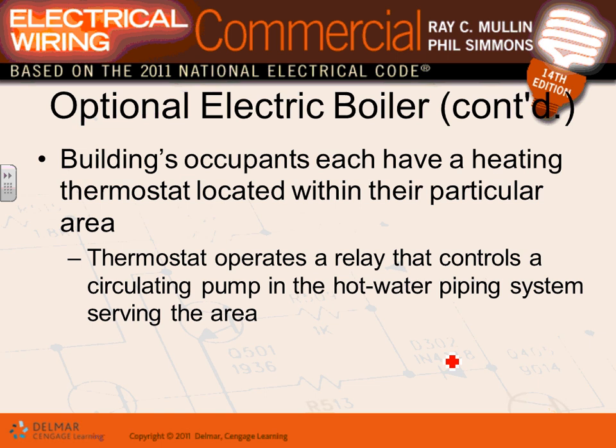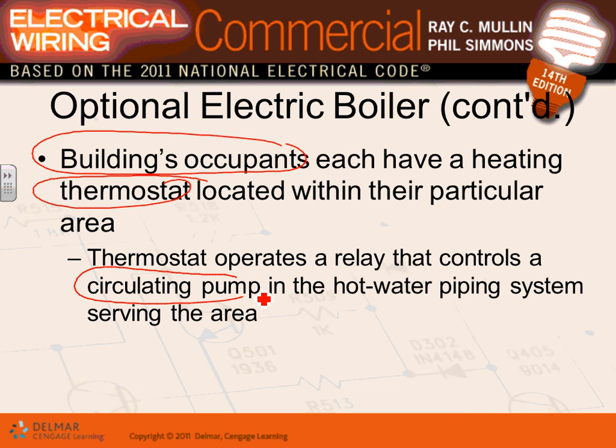So how does it work? Thermostat have to be located. Look at this one. Every building occupant has their own thermostat that drives their own pump. Their own circulating pump will be driven by their own thermostat. And then it just sends the hot water to that building, and now you are hot and cozy. How about cooling it? Didn't say anything about cooling. You have to have your air conditioning to cool you. This is just to heat you.